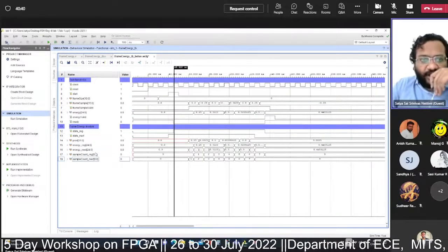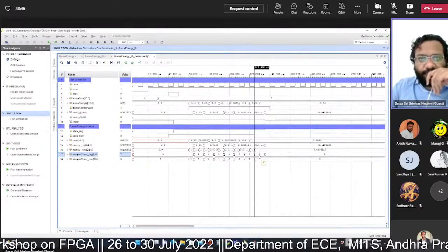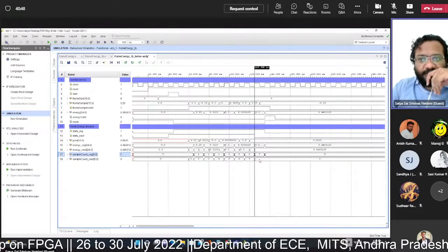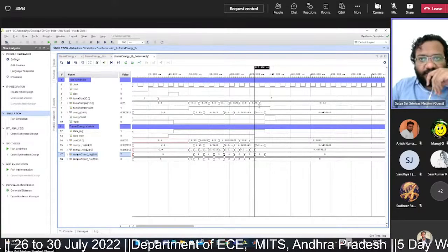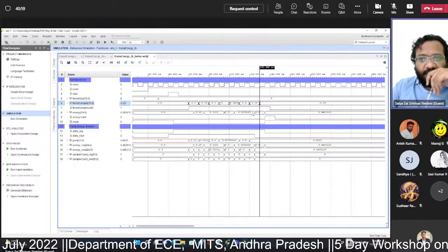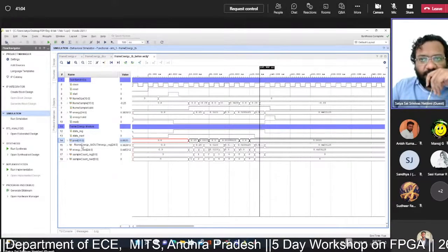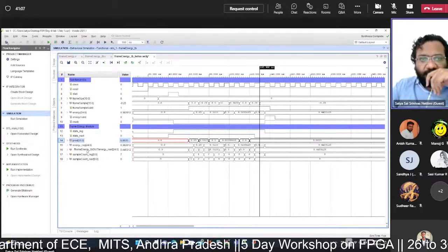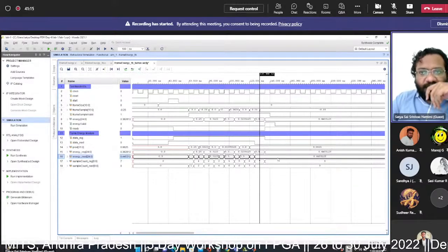You can see here when the count register value becomes 7, it has already received the 7th sample, that is the last sample, minus 0.25. For that it has already calculated the product value, that is 0.0625, and the energy value is also computed, that is 0.4453, and this value will be updated on the next arrival of the clock edge.